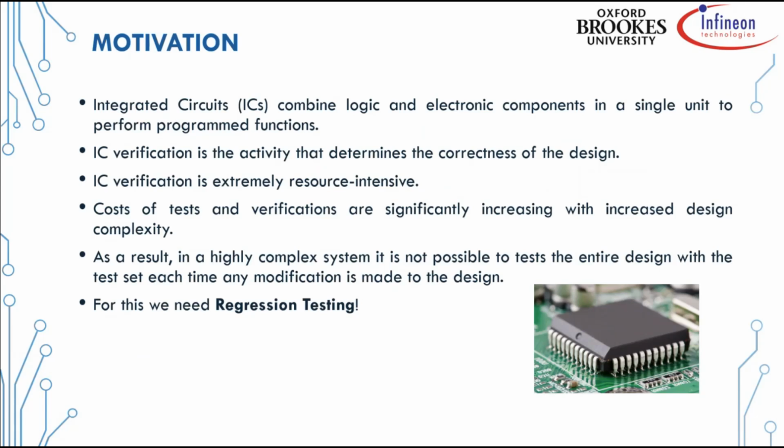Right, so integrated circuits are combinations of electronic components, and that basically performs a specific function. And IC verification is a process of ensuring the design is correct. However, verifying that an IC design is correct can be very resource intensive. So when the design becomes more complex, the cost of testing is also going to rise, and it becomes nearly impossible or impractical to test the entire design every single time you make a minor change in the design. So this is where we need regression testing.